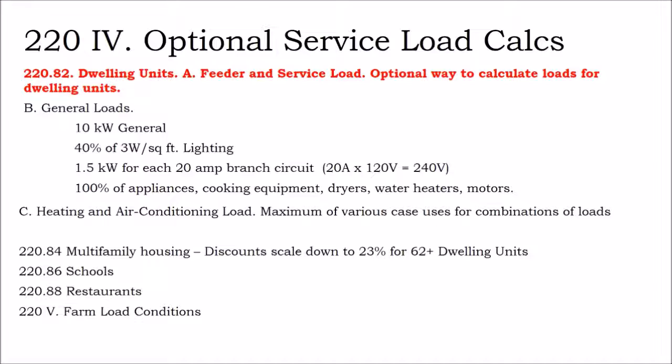It also might mean that if we're generating energy on site and we are managing our energy with a battery bank, some of our home electric services are going to start to look pretty oversized. If you're an energy efficient home and you're fine tuning your energy use, you might find that your home is only using 60 amps of power, but you have a 200 amp electric service.